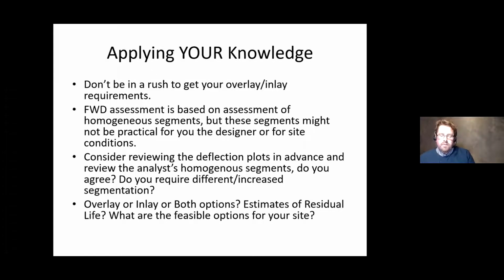Or do you require different segmentation? What's going to work? You're never going to have your visual inspection segmentation matching your FWD. You can, but it's very rare. But if you require extra segmentation so that you can slot one into the other, that can be very doable if you speak to your FWD operator in advance or during the process.